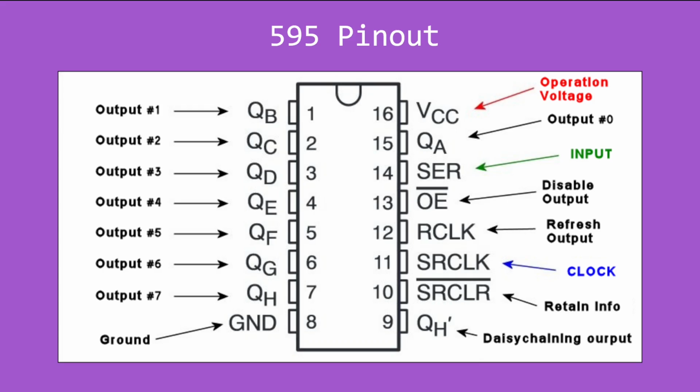And each pin serves a particular purpose. So with a 595 in a PDIP package, this is what the pins would be. So I mentioned the outputs, and there's 8 of them. And then you got ground, you've got VCC, you've got one of the outputs on the other side, because in this case, they want a convention of VCC on one end and ground on another.